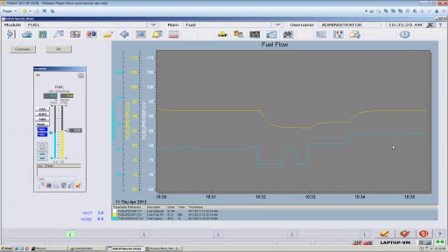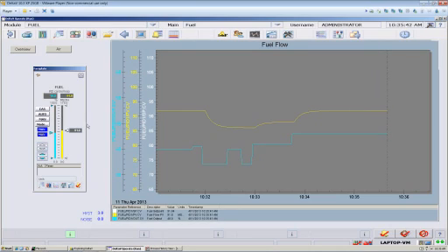For the sloppy valve that I'm showing here, my rule of thumb is if it's 1% or less, I can live with it and tune around it, but I'd prefer better. If I found a valve like this simulated valve that had 3% slop, I would schedule that to be rebuilt, repaired, or replaced at our next outage.